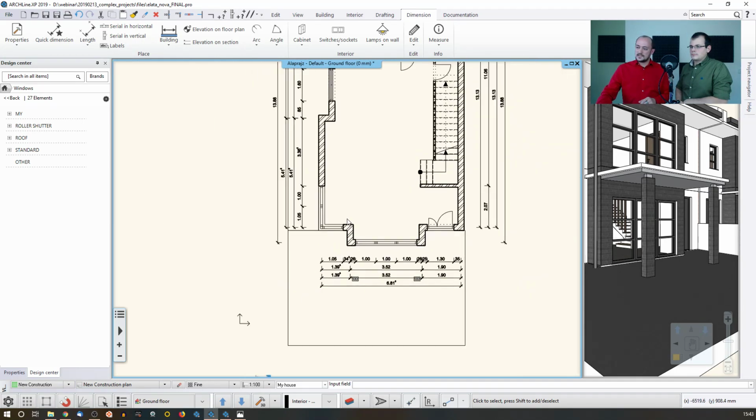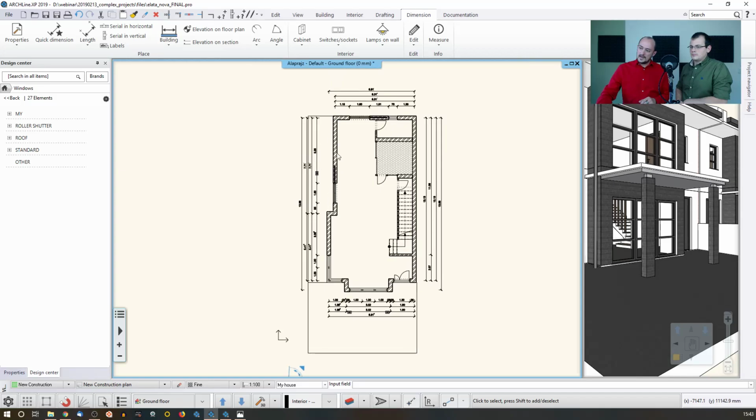That comes the same at the left hand side, where I have an elevation with kind of an extension, which normally otherwise wouldn't be measured. But this way, with the last option, the software will always create a sum of that dimension, the length or width of the building. Very useful. Yeah, so this is how you can use those two values.